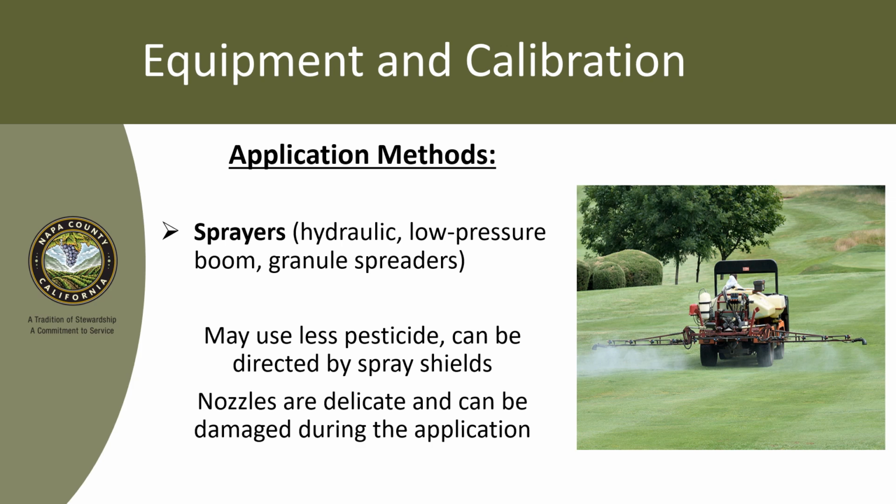The downside is that the nozzles are delicate. They're exposed out there, and they can be damaged during applications. And remember that wettable powder thing that's already doing damage because it's abrasive. So the nozzles require a lot of special care.